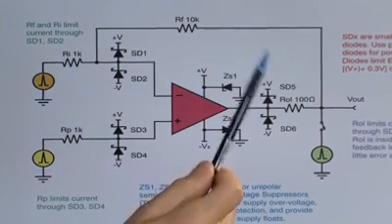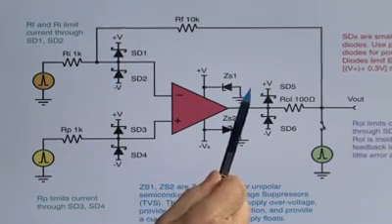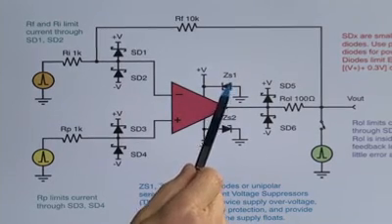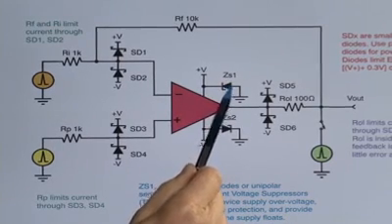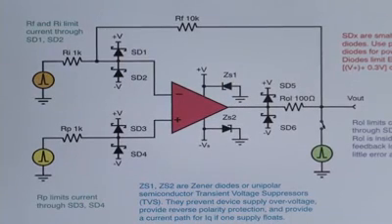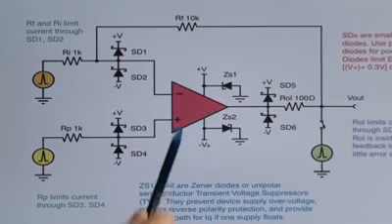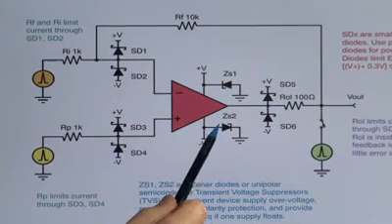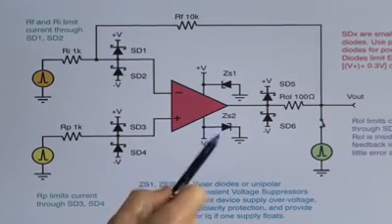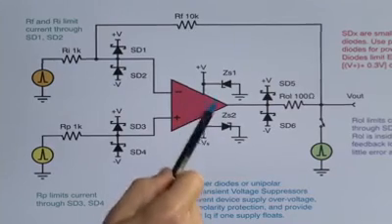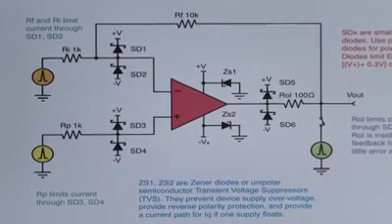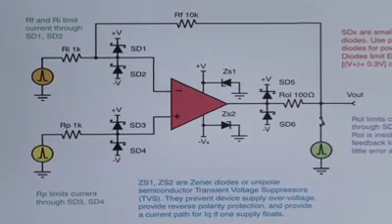When it comes to the power supply, and EOS in that particular case, we want to use a suitable TVS, a transient voltage suppressor, or a Zener diode. In the case of a dual supply operational amplifier, we would put one on each supply. The benefit of that is not only protecting against transient voltage, but it also provides a current path should one supply come up later than the other. Some analog integrated circuits are sensitive to that.